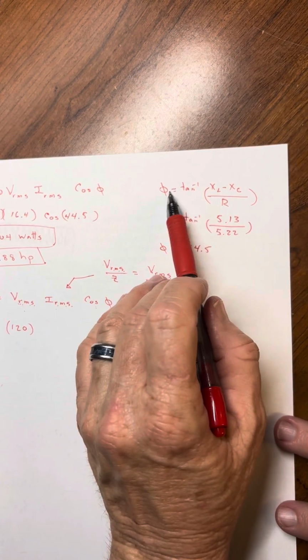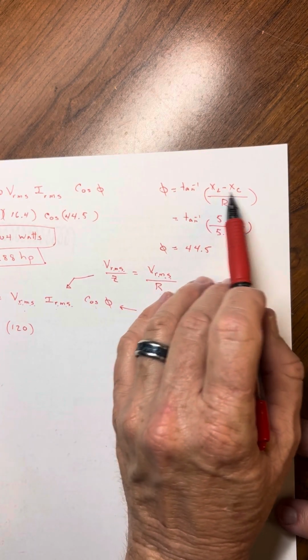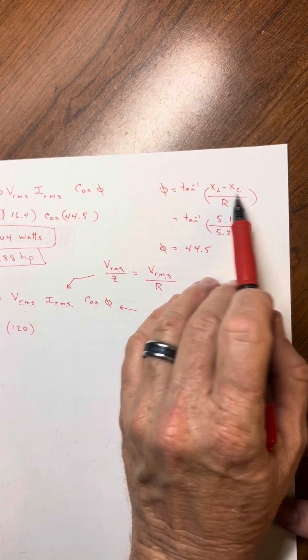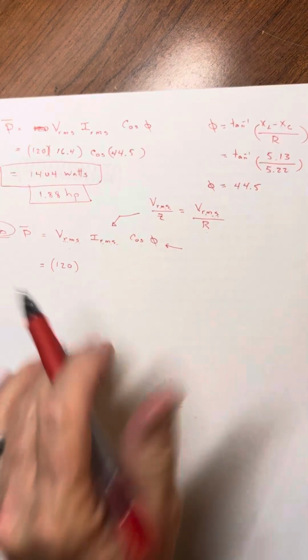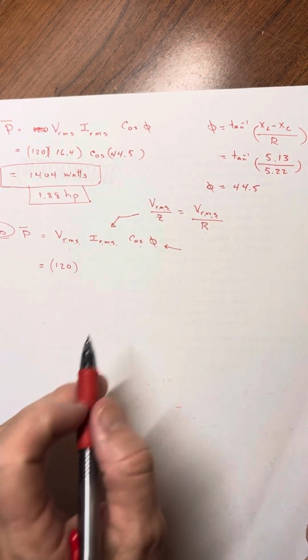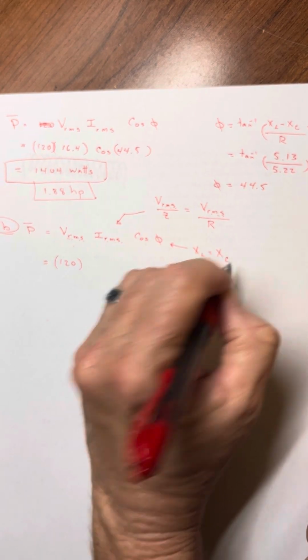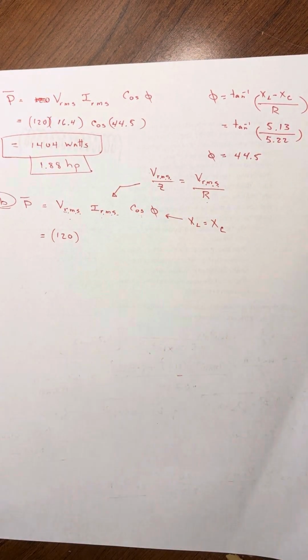And if you look at the phase factor, that occurs when the reactance of the inductor and the capacitor match also. So fortunately, these aren't competing with each other. These each max out when the reactances match.